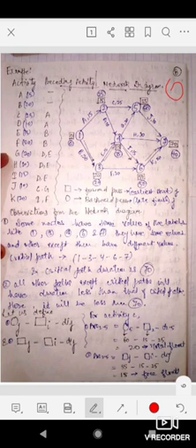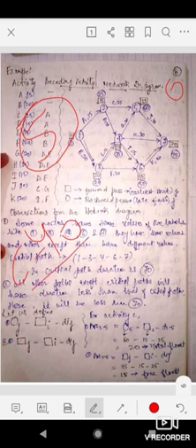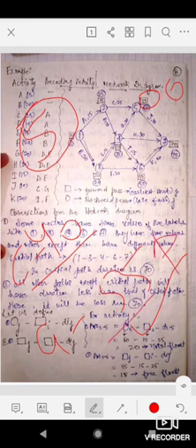Like, see here at node 7. I have taken 70. Or you can come to node 5 first, then I will go to 7. At node 5, activity C will take 25 days, so 15 plus 25, it will be 40. Activity C will be finished after 40. And activity G takes how much time? 35 plus 20, 55. So at node 5 both C and G will be done only after 55. That's why I have taken 55 here. So we will take the maximum of those two.